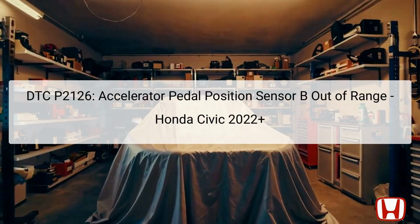The diagnostic trouble code, DTC P2126, indicates an issue with the accelerator pedal position, APP sensor B, which directly relates to the throttle position, TP sensor E. This code is specifically triggered when the output voltage from the APP sensor B falls outside a predetermined range defined by the vehicle's powertrain control module, PCM.